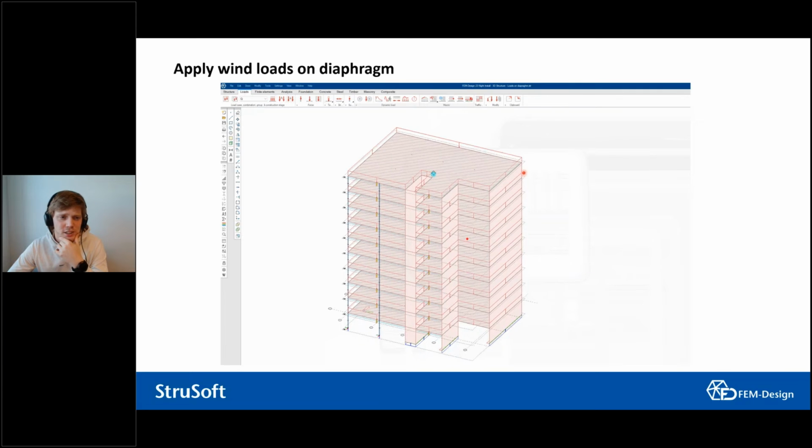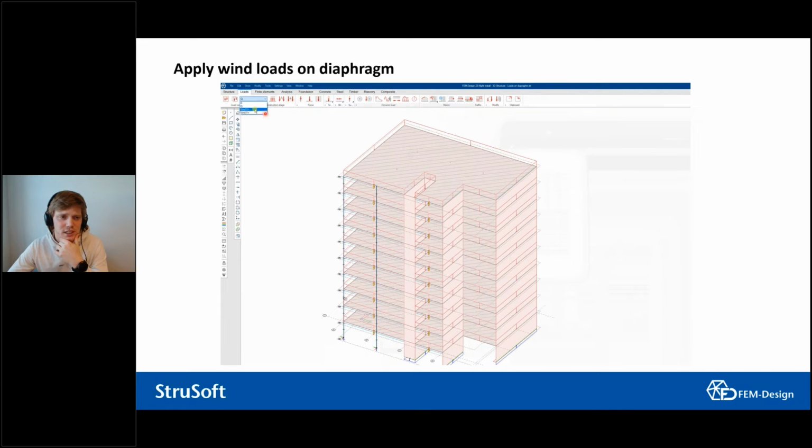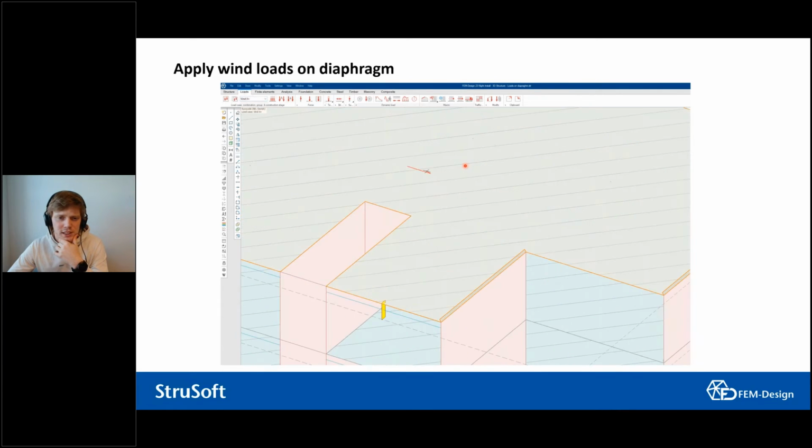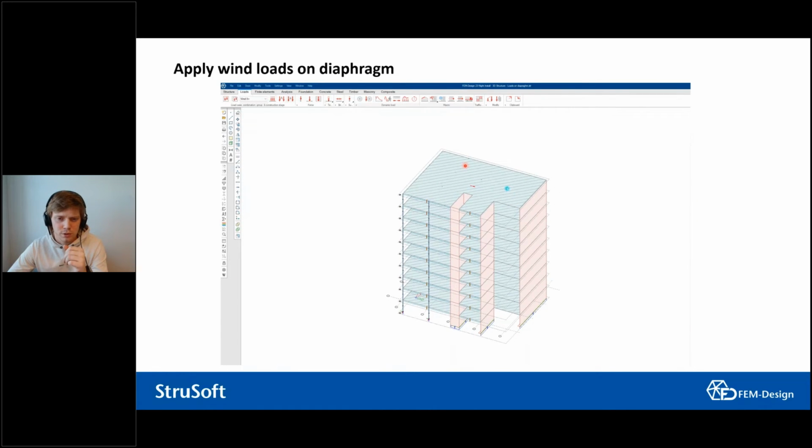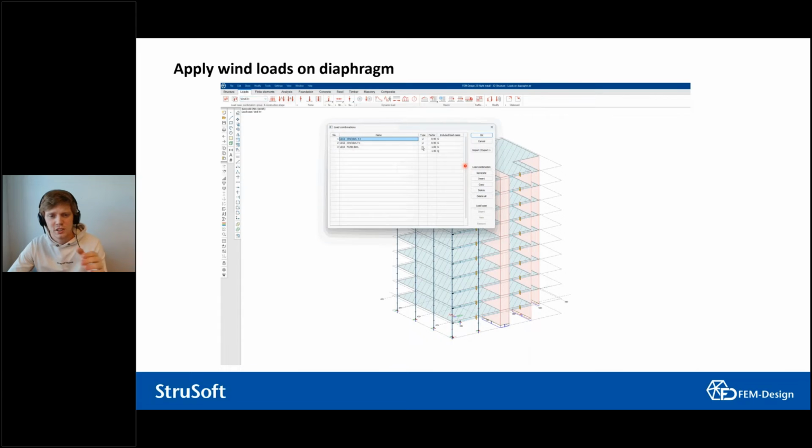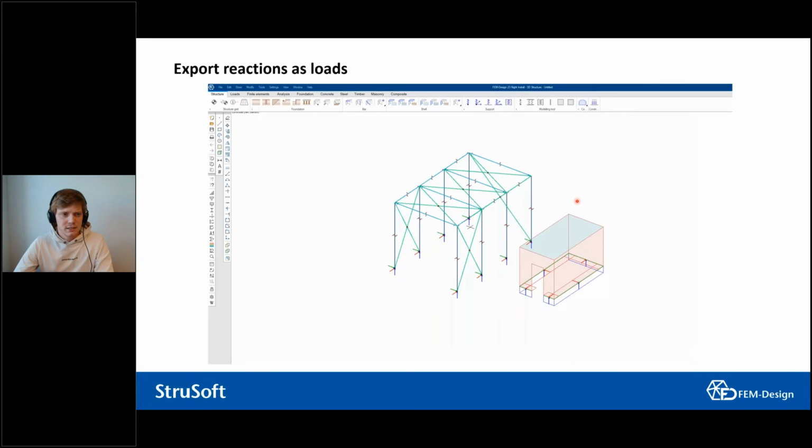And I click OK, and you will see it has created now 2 load cases for me, and it has the load where I want it with the value I want. So this one, of course, will work if I put the diaphragm to rigid in the membrane. It will be a stiff plane. So yeah, that's a nice feature.